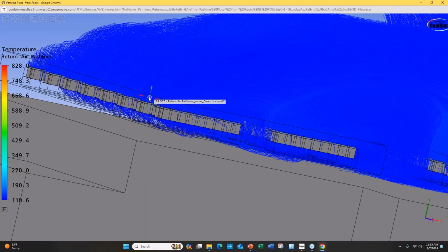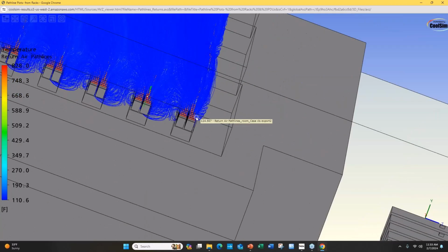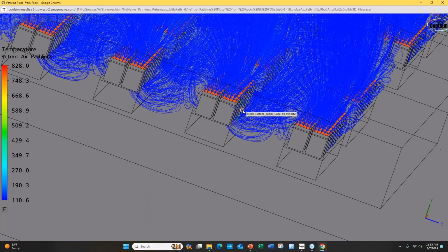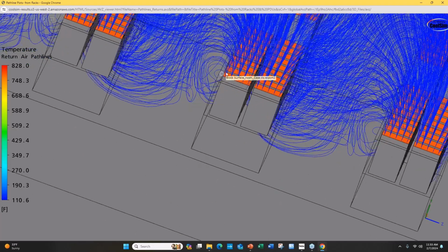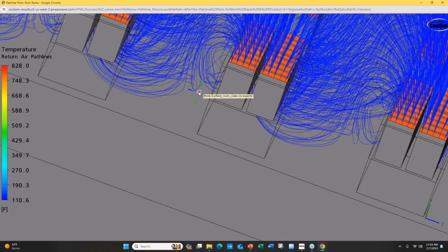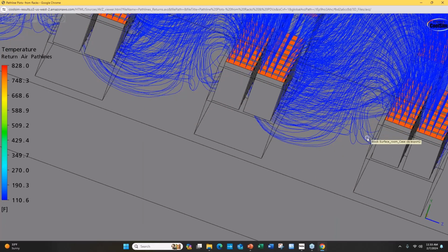And then what you say is, okay, what do I do to solve it? Well, just like in hot aisle, cold aisle containment, yeah, you can see them going down right there. See how that one goes right down underneath? This is a very common thing that I see, is the exhaust gets sucked into the intake. The reason for that is the intake, of course, is running at a lower pressure. And the other reason for that is usually a screen right here, which there is in this case, and that screen is causing a low pressure on the back side of it. So down low near the surface of the roof, you've got a lower pressure than you do up on top. And what that does is tends to pull the air from the exhaust down into the bottom. So they just recirculate on themselves, causing efficiency to drop off quickly.